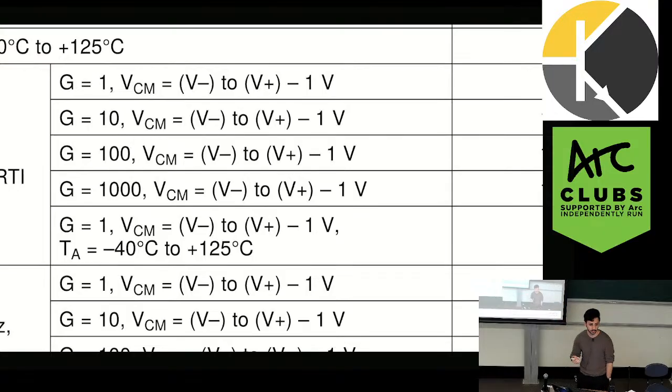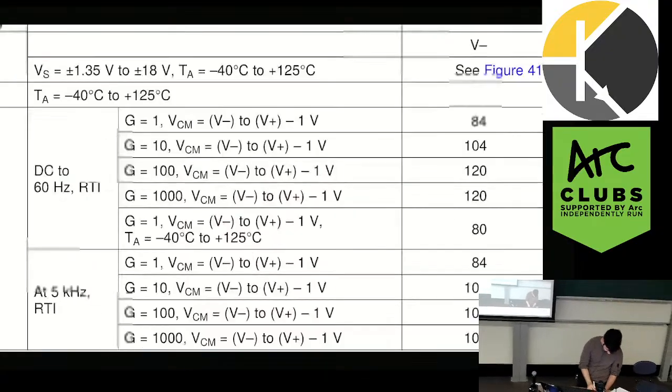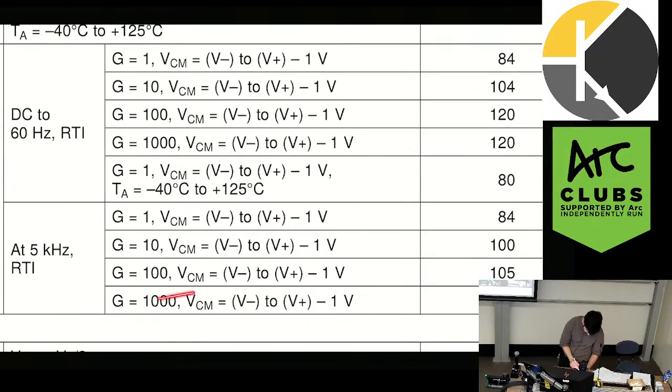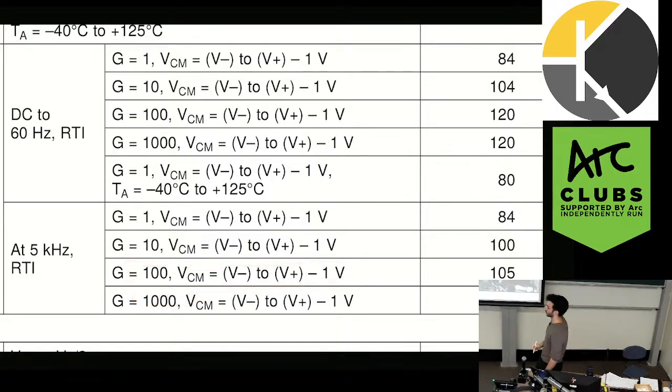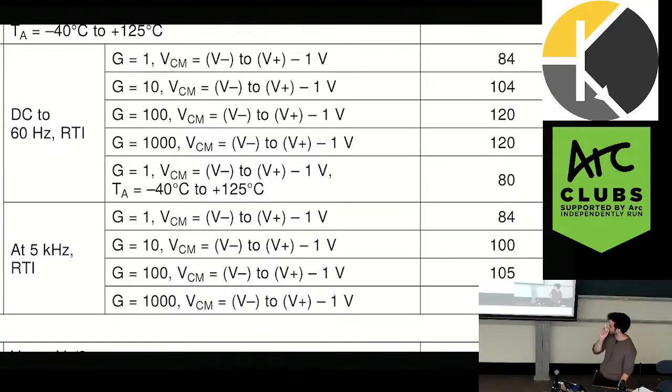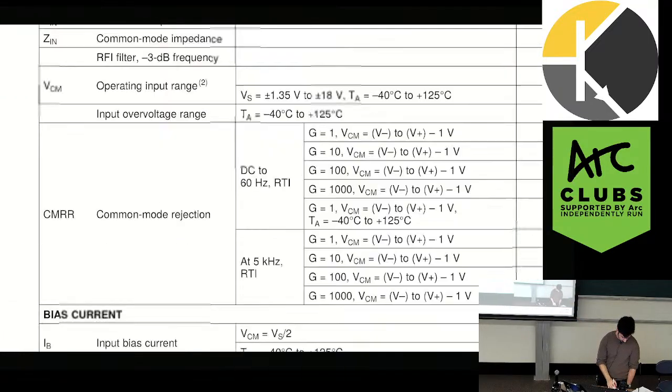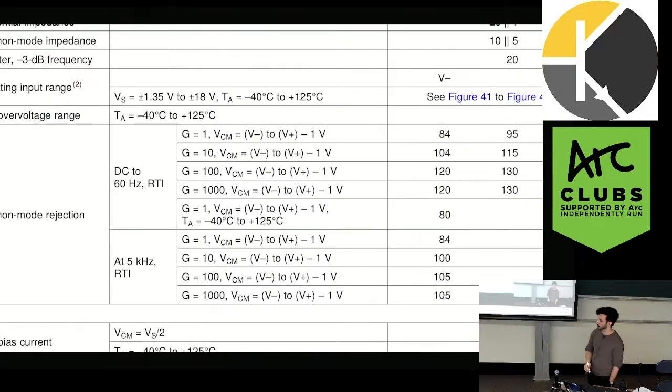And that's it. Where does your assumption come from? I looked at the next question. But even if you look at this one, you can see it's the exact same anyway. But the next question says use 50 hertz or 60 hertz. Yeah, I probably shouldn't have said use an assumption because it's the same at either frequency. What does change on frequency is the common mode rejection ratio. We'll get to that later.